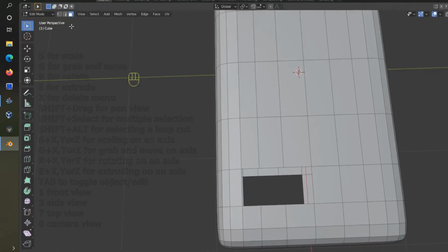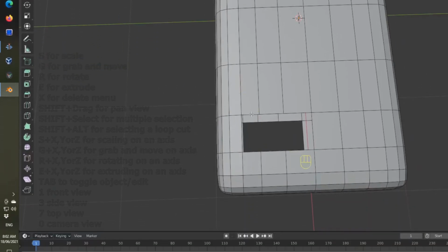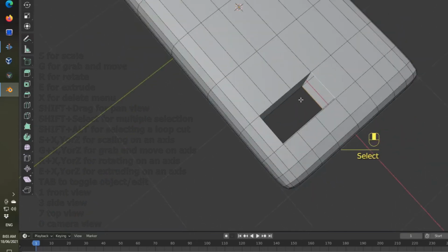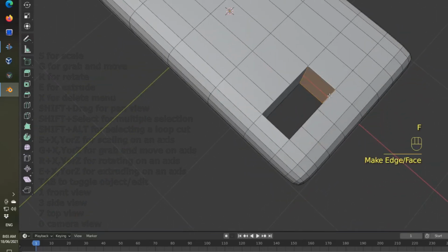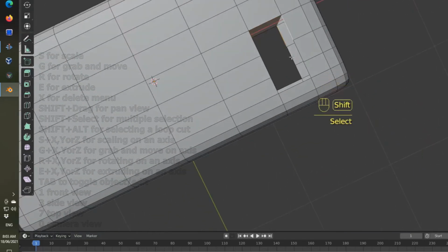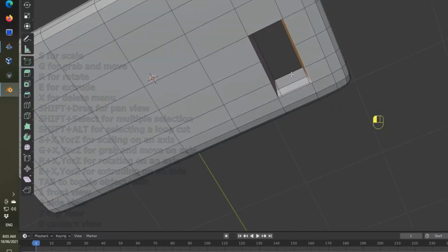Now we're going to select the edge mode, edge select tool, and we're going to select the edges of the hole, and we shift click, but make sure your first selection is never shift click, then shift click. That way you'll only get what you want to select. You won't get something else that you've accidentally selected. Work around the hole until you've got click, shift click, shift click, shift click. First one, don't have shift down. You have gone right round.